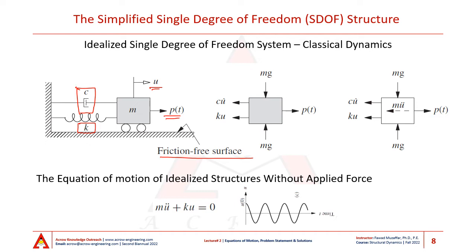Now, the free body diagram of the mass is shown adjacent to this mass trolley system, and this is basically resisting the weight of the mass. So, this is basically the reaction of the wheels. This is the applied load. The damping acts in the direction opposite to the direction of the velocity, and then this is the force associated with the spring.